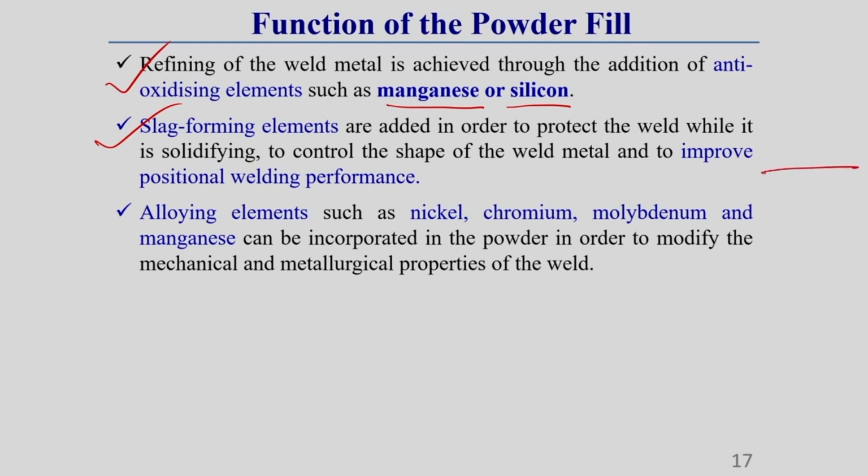as well as this weld pool. Over this weld pool there is a slag layer. As this slag layer covers the weld pool from atmospheric contamination, the chances of oxidation and other things are prevented. This slag also protects the weld pool and reduces the cooling rate. Once the cooling rate reduces, an annealing type of effect takes place in the weld pool region. Due to the annealing effect, this weld material zone is comparatively more ductile than other exposed weld material. What I am telling, understand?